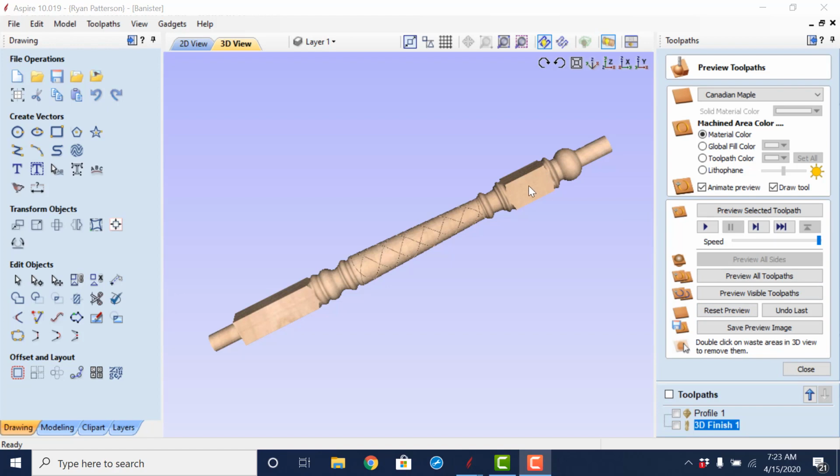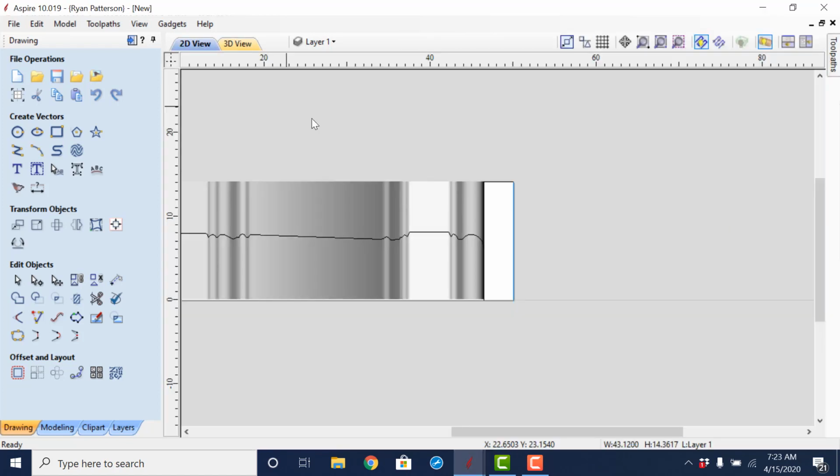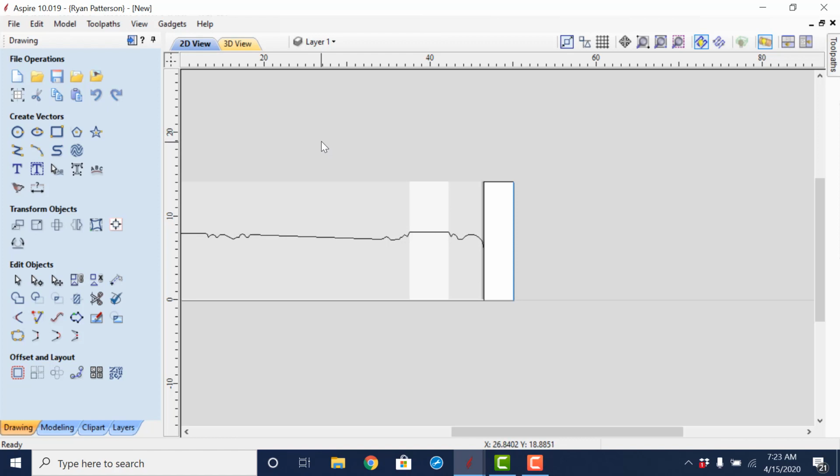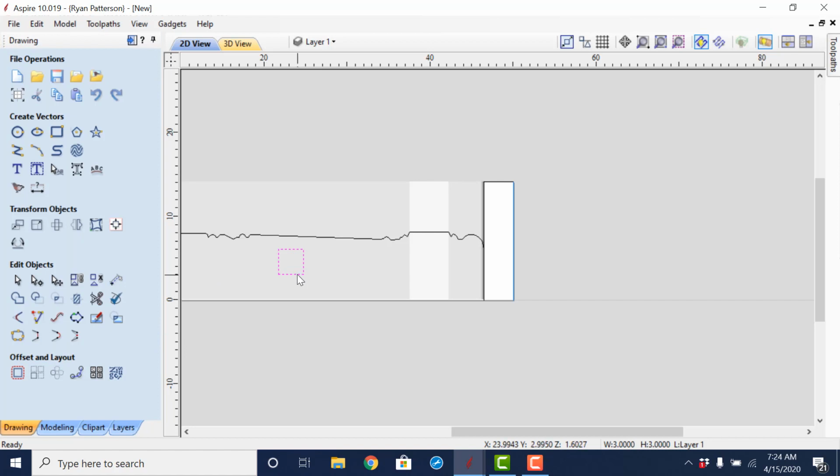Alright, so our next step is to create a square profile across the top of our new model. And to do so, we're going to have to do the similar thing that we saw when we imported that square post. We need to be able to unwrap a square and get that scallop type of cross section. We could do that by drawing a square. Draw out a square. I'm going to make this square to be 3 by 3, selecting apply and close.